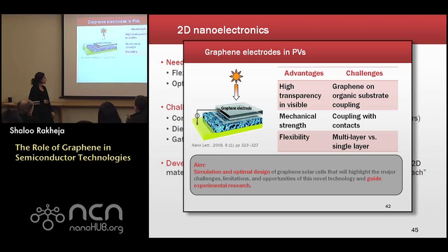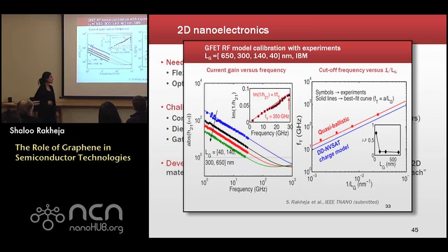Okay, so then zeta is not really a specific parameter that you're fitting, because you said there are 7 parameters that you were fitting. But that's not... Zeta we are actually extracting only from the S parameter measurement. So zeta is the only factor that we get from this measurement, while the rest of the parameters that go into the dynamic model come from the transport formulation. So if we didn't have that, we would not be able to reproduce this very nice fitting that we see over here. That ballisticity varies from very low to very high, and it has to be between 0 and 1.